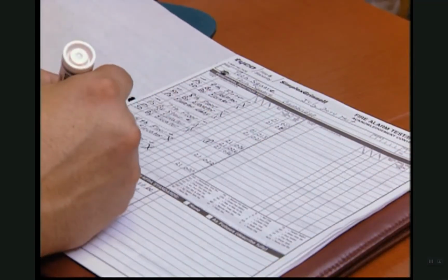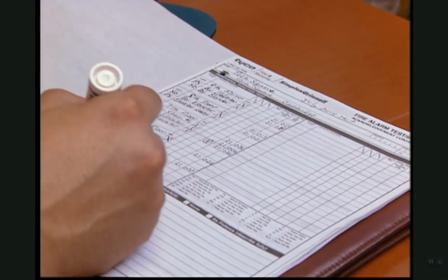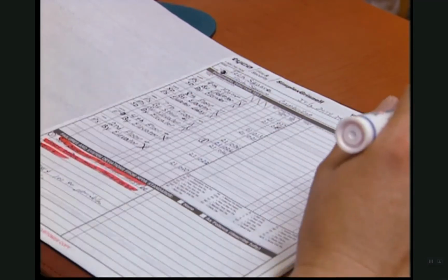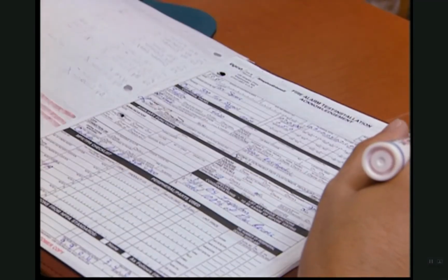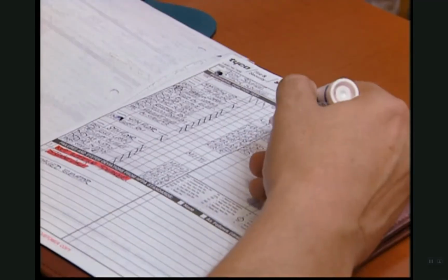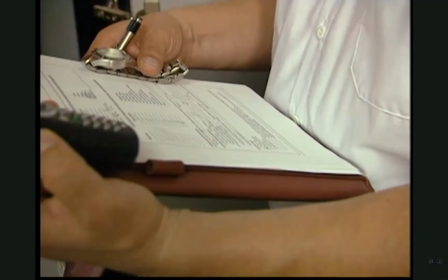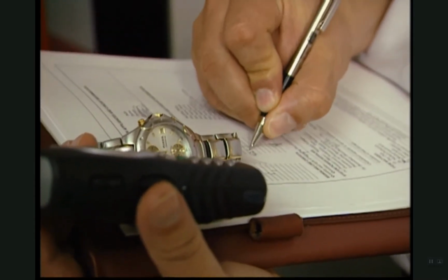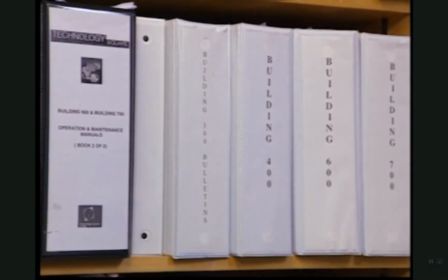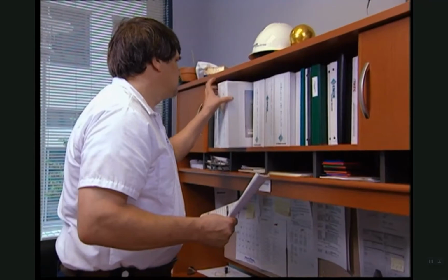Record keeping is an essential part of any inspection and testing program. You need to create comprehensive inspection forms that cover all components of your facility's fire alarm system. During inspection and testing, follow your checklist so you don't overlook anything, and record the date, time, and results of each inspection and test. Keep the forms on file.